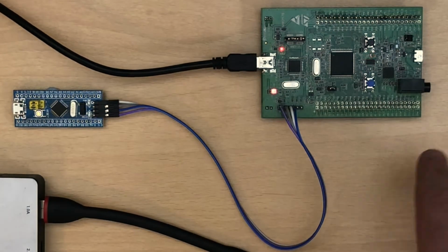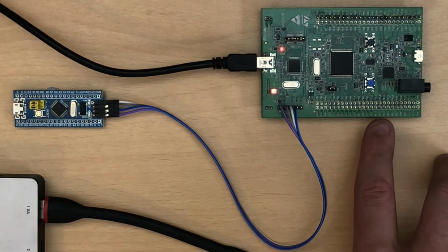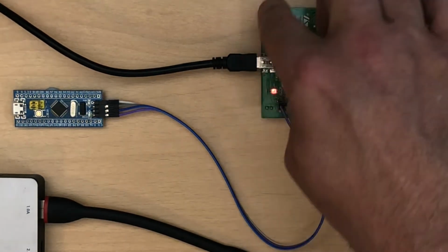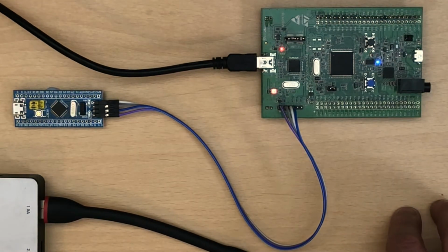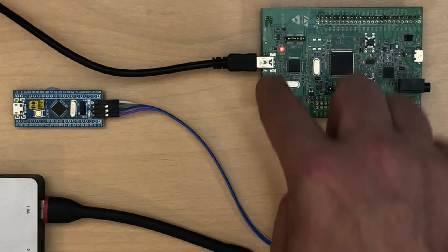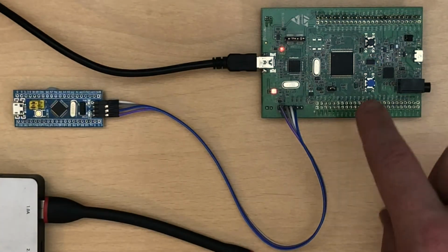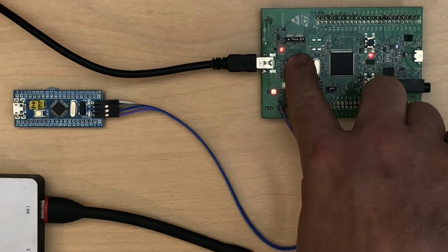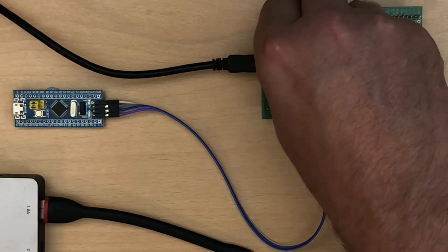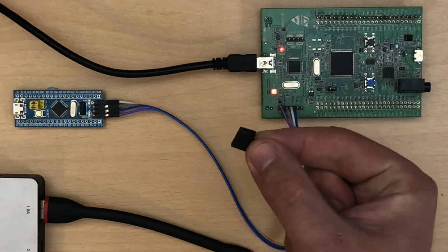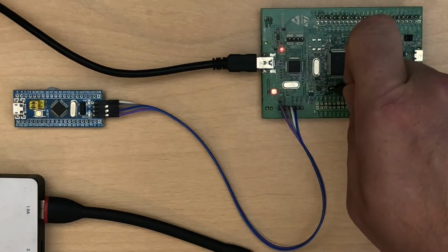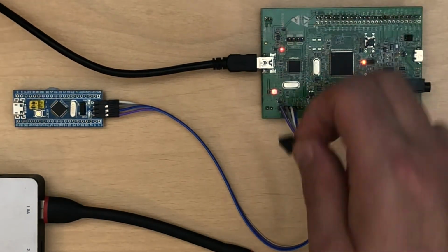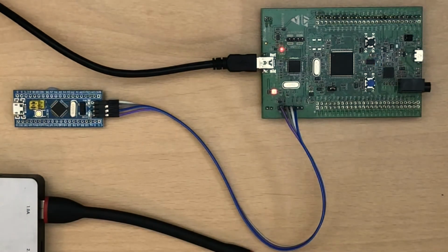So if you have one of these ST discovery boards or one of the Nucleo boards with an ST Link hardware on there, we can use that. Essentially, if that's hooked up to the computer, and we'll see that connect in a minute, you want to remove the ST Link jumpers, these little linky bad boys, because these are used to say we want to connect the ST Link to the onboard microcontroller, and we don't. We want to connect it to our BluePill device, so we'll take that off.